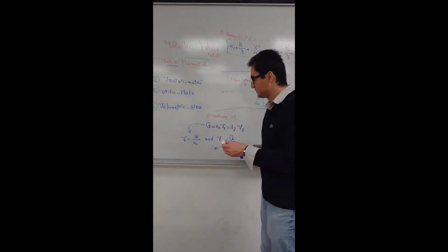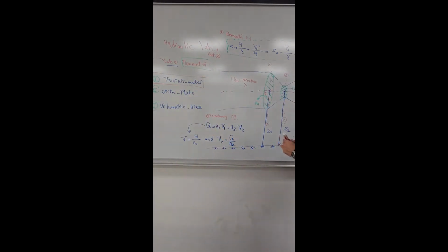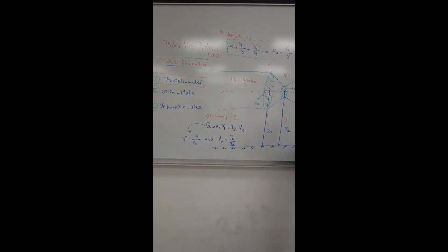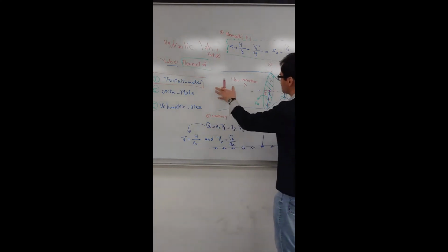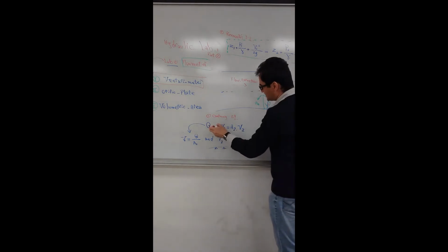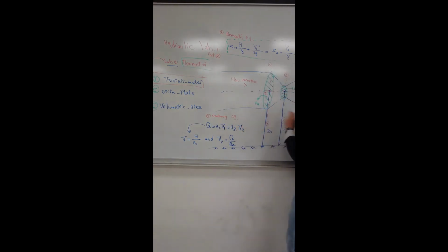For the venturi meter, if you look at the continuity equation, you can see discharge is all the time the same. Discharge passes through the venturi meter from any cross-sectional area. So Q is equal to area 1 times velocity 1, equal to area 2 times velocity 2, and so on: area whatever you have times velocity of that cross-section.